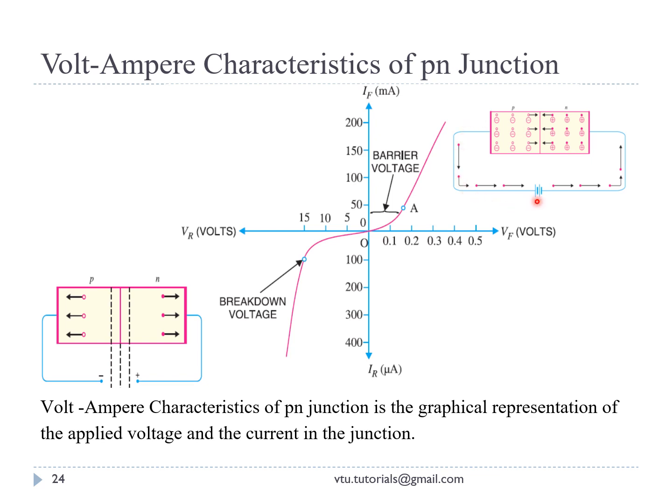So there will be a small current flow. It starts to give a flow of current. At some forward voltage, that is 0.7 volts for silicon and 0.3 volts for germanium, the potential barrier is altogether eliminated and current starts flowing in the circuit from here onwards.